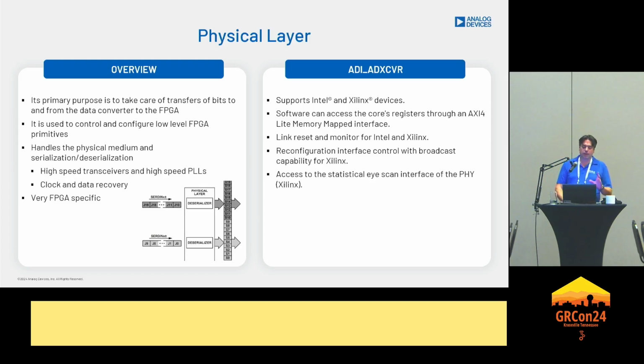And while it is so FPGA specific, we created a common HDL IP core around those very specific transceivers that you can find on the next slide on these different FPGAs and give them a consistent look and feel to the software. That's done through an AXI4 memory mapped interface.